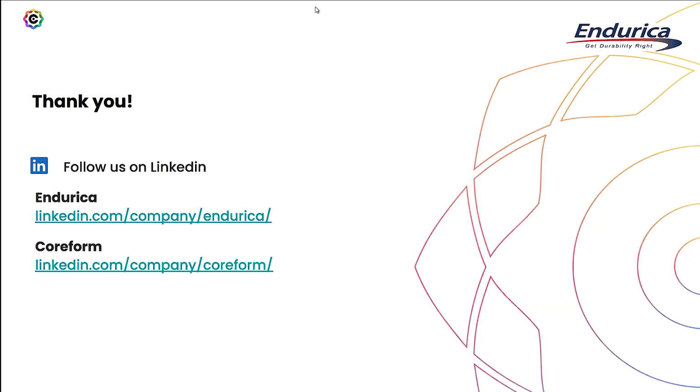Yeah, Cubit does support quadratic elements, and so that would have those mid-side nodes, and it supports both the hex 20 and hex 27 types of quadratic elements, and you do have some capability to shift the nodes beyond just what the standard projection to the CAD geometry boundaries are. That part is probably better left to a power user who's going to be using the Python interface.